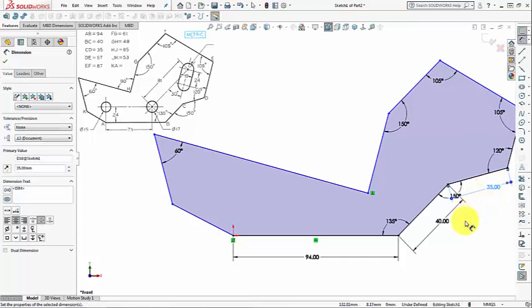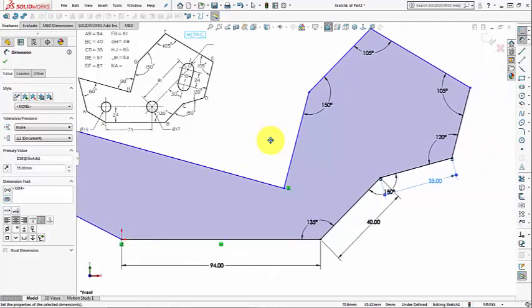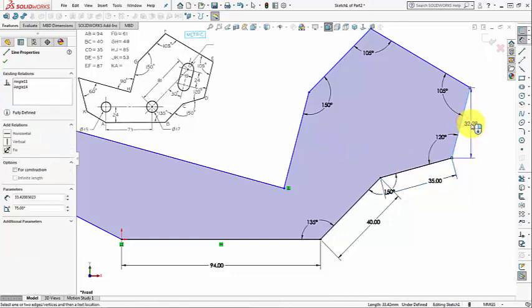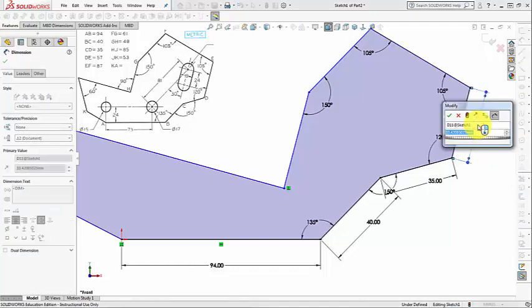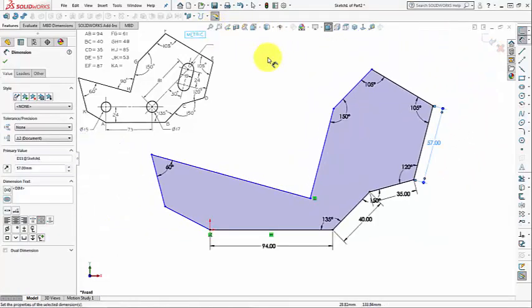Okay, we can zoom, or we can press and hold Control key and then pan my sketch. Then for this line, remember, be careful, it's not the vertical distance, it is this distance. So the align distance. So right click and then drag your mouse. Then left click, and DE is to be 57. Maybe zoom to fit. Okay.